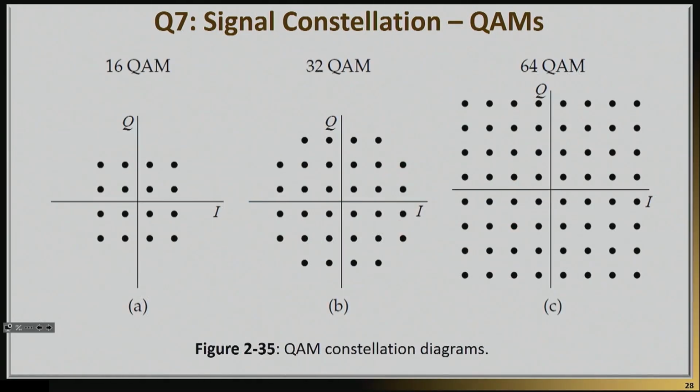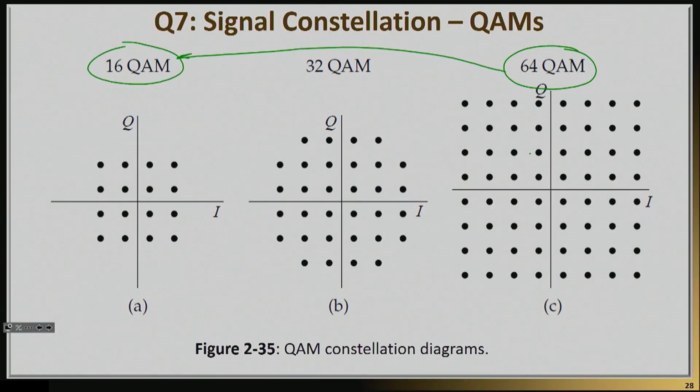These are a few other signal constellations you will see out there. And again, once you see enough of them, now you can start understanding, for example, why a system might actually go from a 64 QAM to a 16 QAM if the noise increases. It's because in the same space, I will put basically fewer symbols.